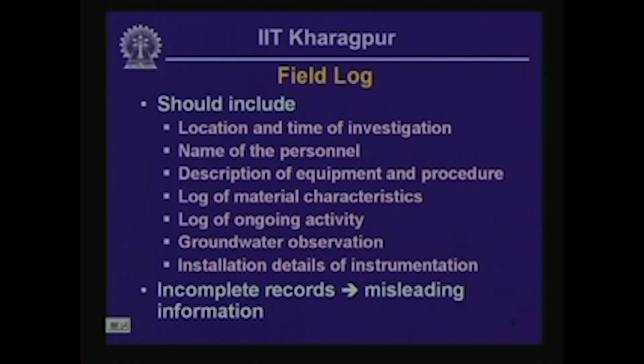The second thing that must be included on the field log is the name of the person who is logging, as well as the name of the driller, because if the designer needs some information regarding activities which are not appropriately mentioned on the field log, which are missed out from the field log, in that case the personnel who signs off the field log can be contacted.